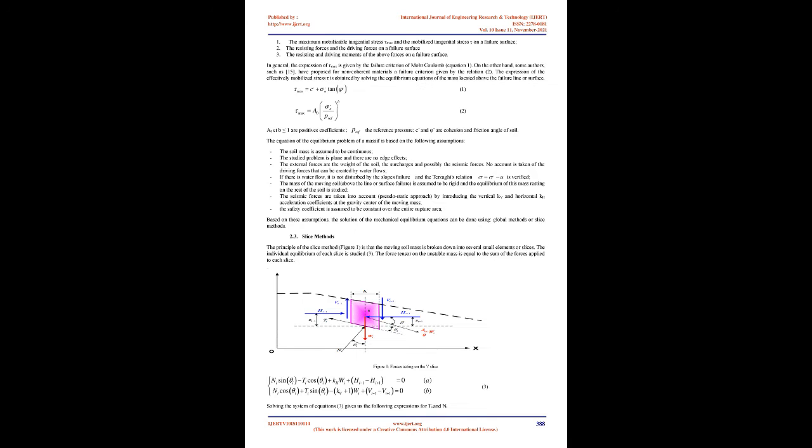their probability of failure. This stability analysis can be performed by 2 methods, one probabilistic and the other deterministic. The probabilistic approach is based on the spatial uncertainties of the mechanical and physical properties of soils, which result in an uncertainty on the representativeness of the calculation results. The implementation of this approach is very difficult and it is understandable why it is not often used by civil